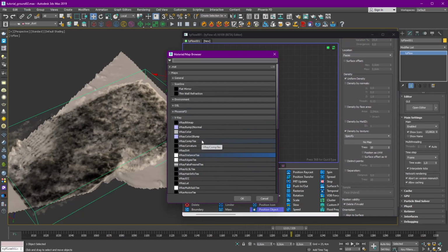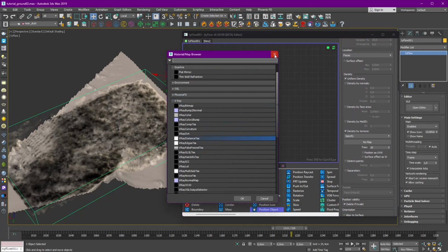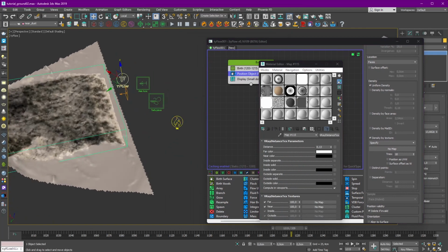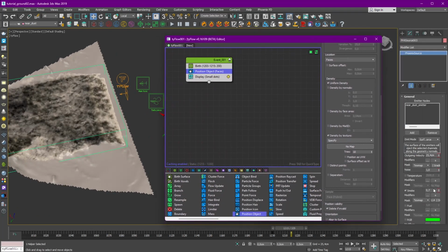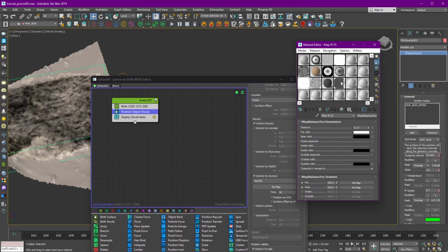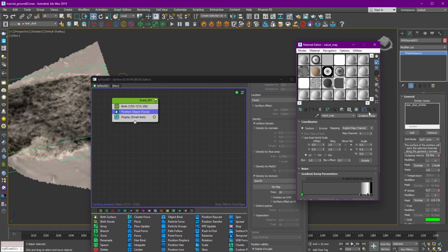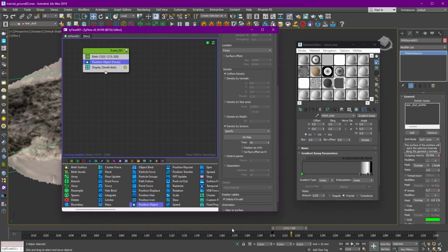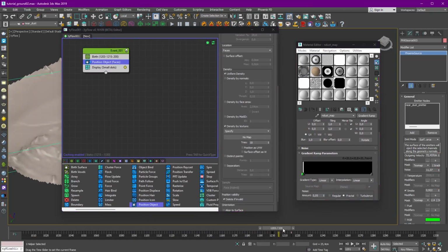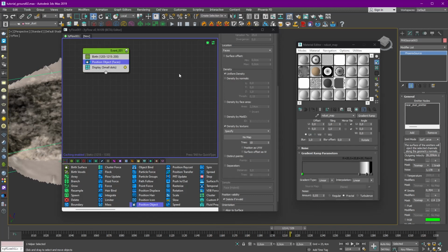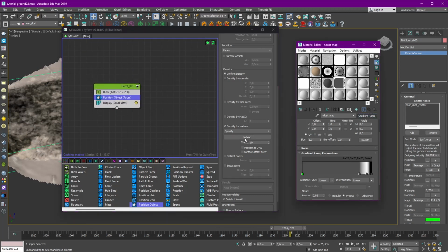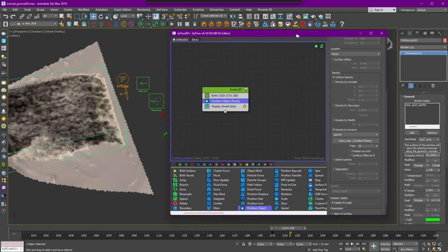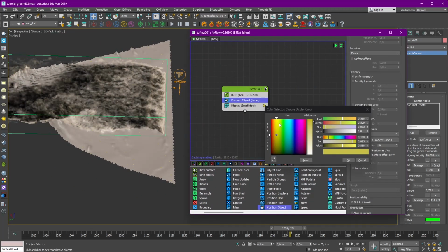And inside the slot of this map, we need to actually input the gradient ramp, but I think we can use the same map as we used in the source from this close up dust simulation, because actually it's the same gradient wave. So I think we can use this map. Yeah, actually this is it. We can use it. So just copy actually instance to this slot.